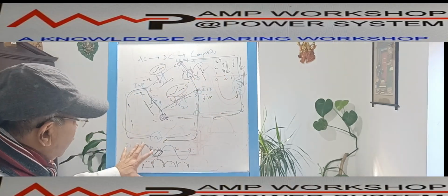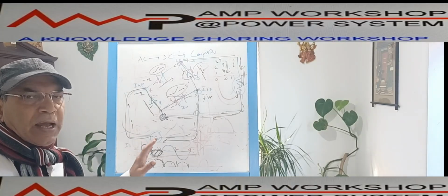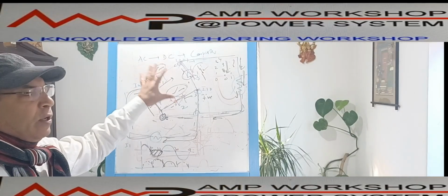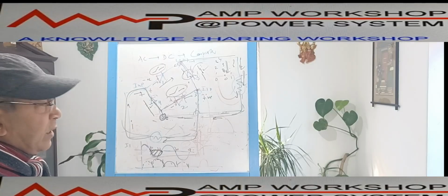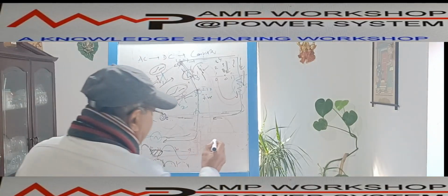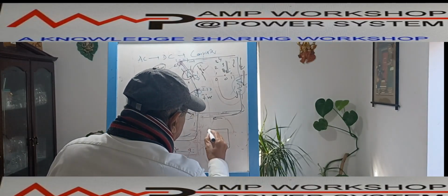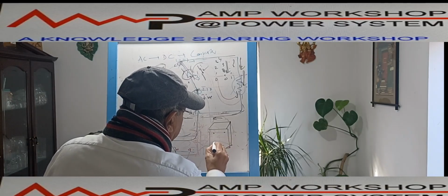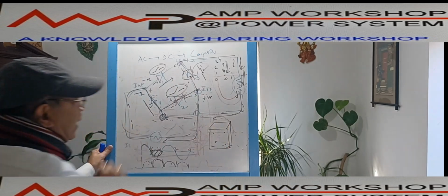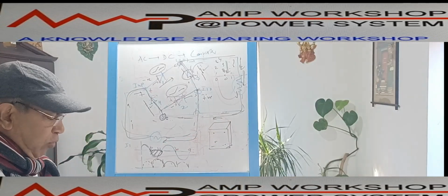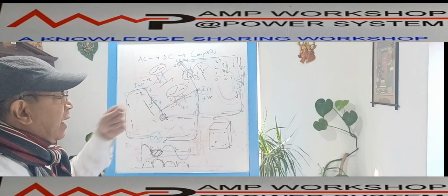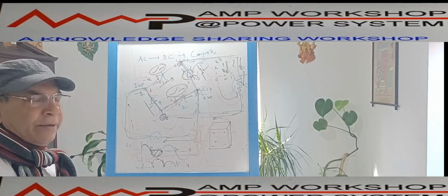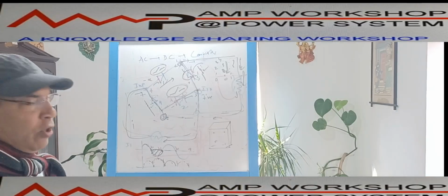That's why for most of the critical and emergency equipment, or the big or important items, we use a full wave rectifier. And if you see this rectifier, physically it is a small square shaped disc, like this type of disc. Over that there are 4 terminals. These 4 terminals, all are inbuilt within this block. That is the way this diode rectifier block is manufactured. So this is the full wave rectifier. So this is the half wave rectifier and that is the full wave rectifier.